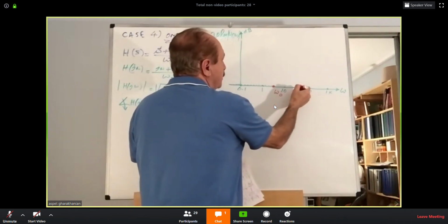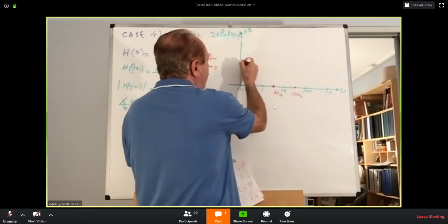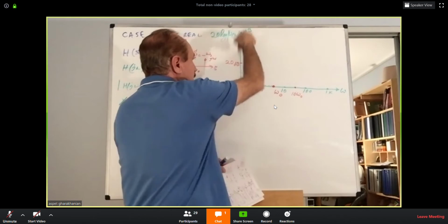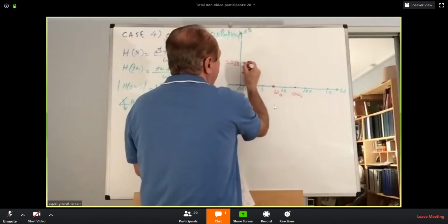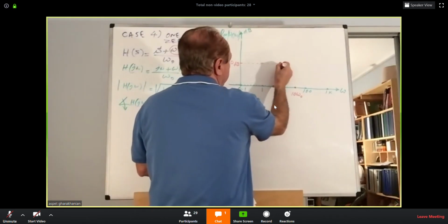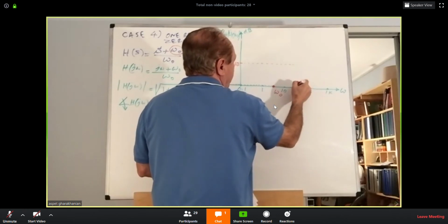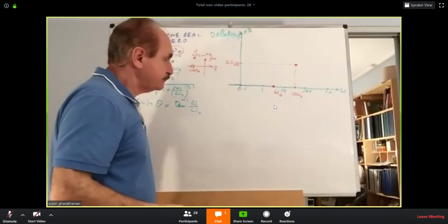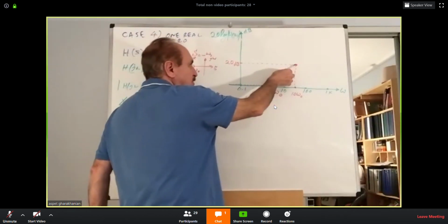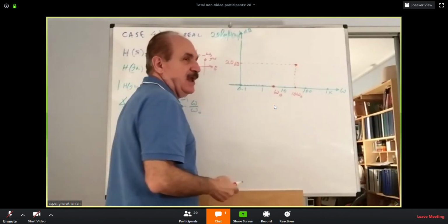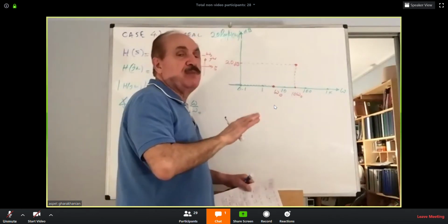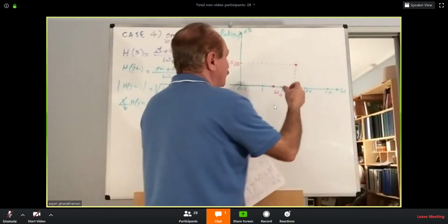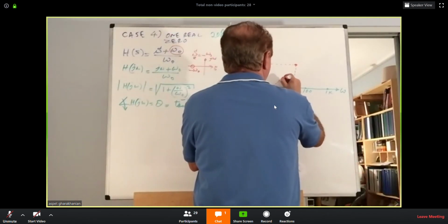Okay. Then you will find the 20 dB on the calibrated axis. Then you will find that spot. The line that joins the two together has a slope of positive 20 dB per every decade, which is this line.